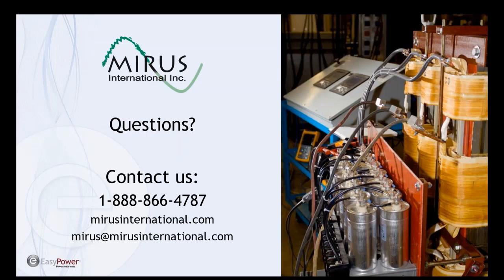The active front end drive needs to have a passive filter, an LCL passive filter, built into the drive. You have to be careful about filtering an active front end drive with another filter, because it already has a filter built into it, and you can create problems.